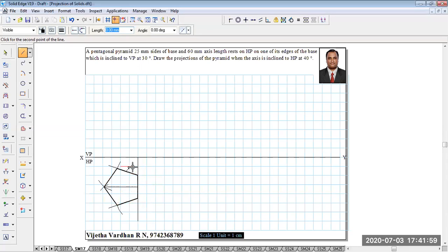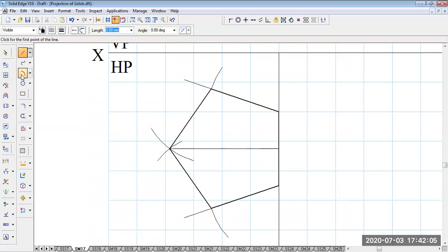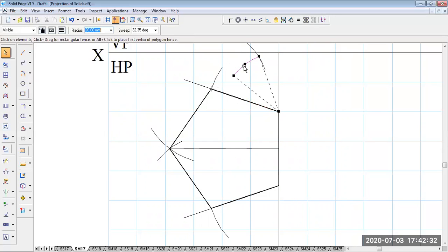Now, if anyone doesn't know how to get the midpoint of a line, let me show you a simple procedure. Take your compass and set the radius value greater than half, and then draw a constructional arc over here using a 2H pencil, and keeping the compass at the other side without changing the radius, which should be greater than half, draw an arc like this. Let me repeat it because there is a shortage of arc length.